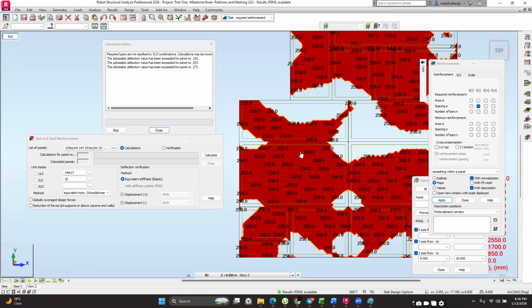Those are the hollow pots, the waffle slabs, the ribbed slabs. You can look at them because they allow for larger depths without being unnecessarily heavy or using too much rebar. So Favor, at the start, you can increase the depth, and if it goes above 200 for normal structures, I'd recommend you look at alternative slab systems, such as the hollow pots, the waffle slabs, or the ribbed slabs.